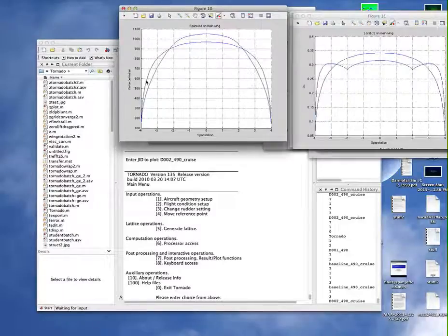This isn't too useful. Let me go out to here. Now, this one that's sort of bowed out or squished down is a rectangular wing. You can see there's larger load near the tips, and you have the force, and then on the inboard side it's less. In the tapered case, we have a larger root chord and a smaller tip chord, so it manipulates this distribution into this distribution. You say, why is it a great distribution? Because the closer it is to elliptical, the closer we are to the condition of minimum induced drag based on Prandtl's thin wing finite aspect ratio theory. And we were able to make this.